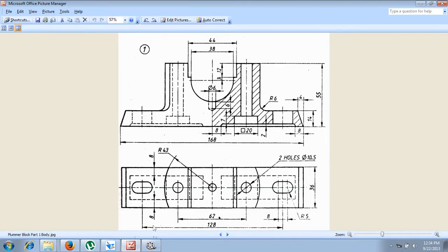While creating the sketch, if you observe the sketch properly, it is a sectional front view, that is, the right half of a section has been created. It is a mirror component on right and left with respect to the center. Now we shall eliminate this cutout, this cutout and this hole and this cutout, and let us create only the hatched portion without considering the cutouts. We can do the cutouts later. Now the hatched portion only is supposed to be drawn first.